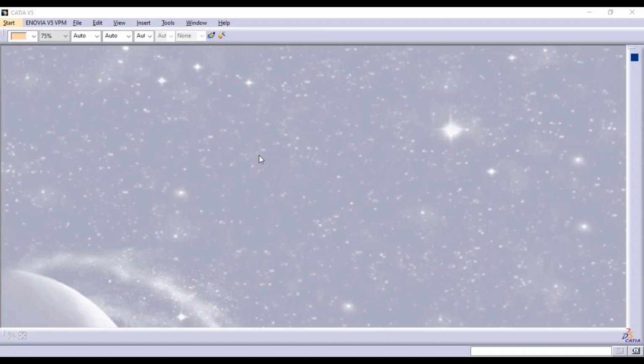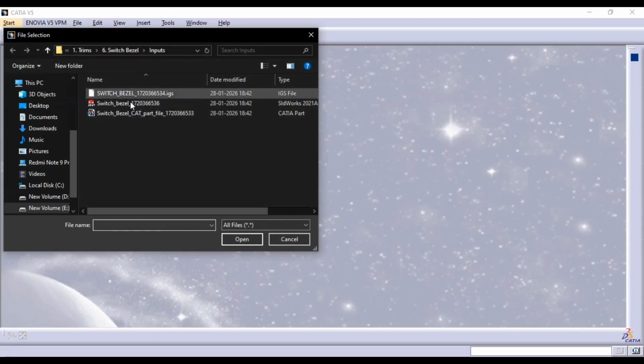So till the last video, tool-wise, we have seen the draft angle consideration and tooling axis creation, the class B and class C creation, and we have approached the way of the closed surface. The class A surface will be given to you, and out of that we will be designing the class B and class C, and trimming all the surfaces one over another. Then finally, we are doing the closed surface option. The same thing that we are going to do here also, but the complexity of this part is a little more when compared to the earlier one.